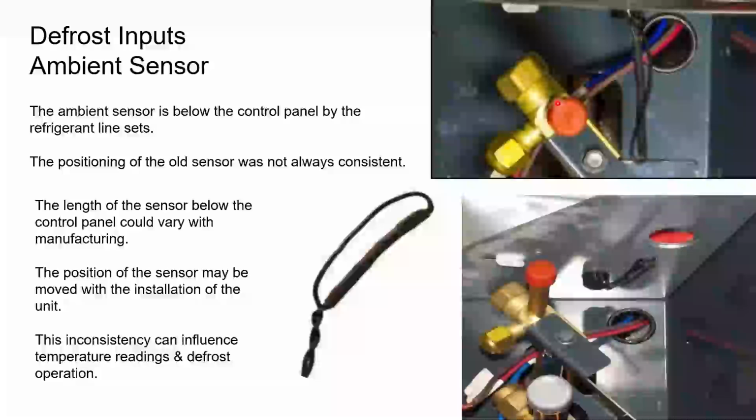Now, I understand we did this on the Trane American Standard products for 30 years, hung this sensor like this, and it worked okay. If we folded it up tight like this, it worked better. But unfortunately, the reality is the factory guys are people and they make mistakes and forget to do things just like all of our people out in the field do. And sometimes it didn't get folded up properly, or something got pushed up against the liquid line valve here, or got too close to the liquid line valve, got some heat off of that, and it would cause some unusual readings. And so we had some inconsistencies.